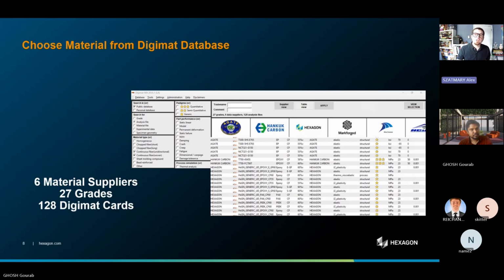Do you have any suggestions on troubleshooting skills, or are there any errors that Digimat users who are new to Digimat seem to make frequently? On the material aspect, if you give non-physical data, for example, that can be a challenge for creating the constitutive material. But Digimat really gives you very helpful error messages when it comes to these material properties.